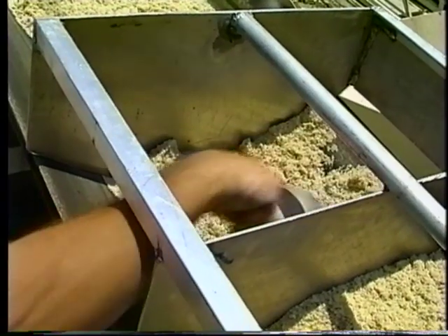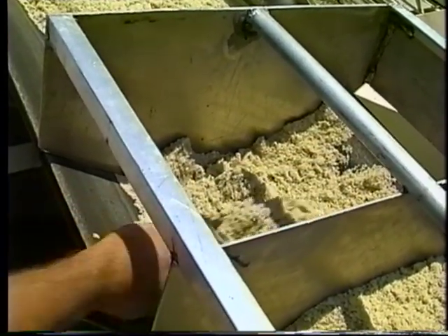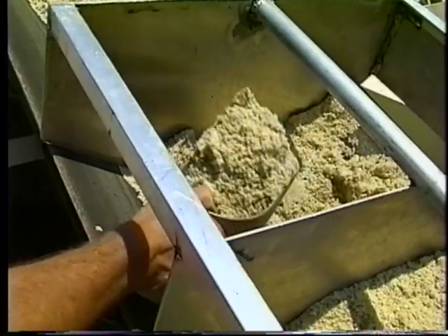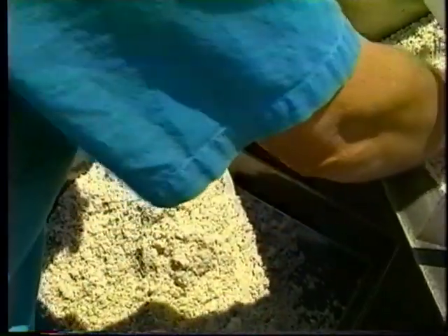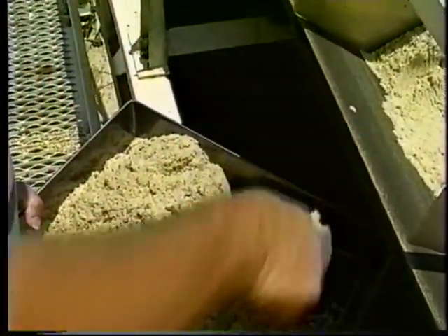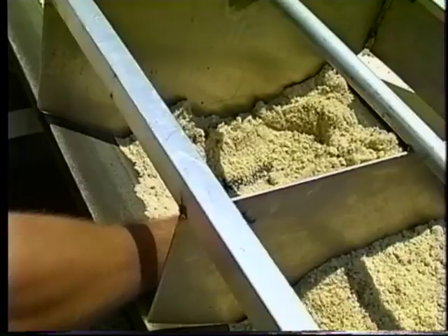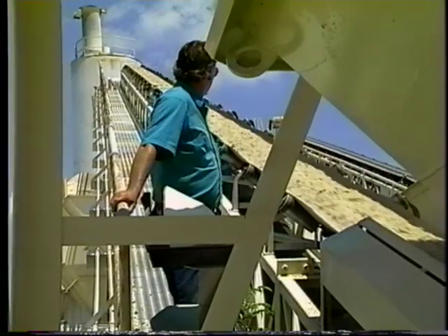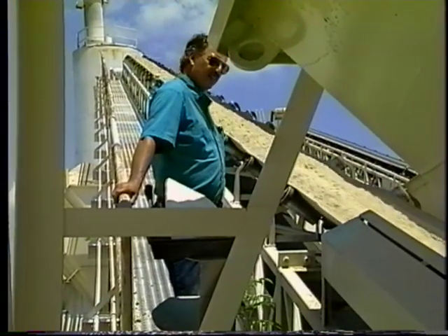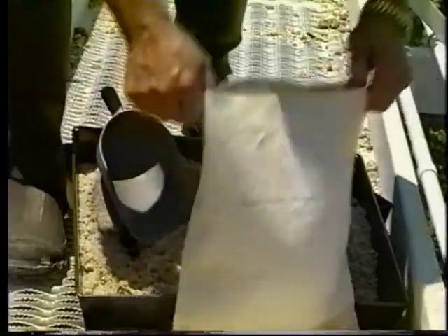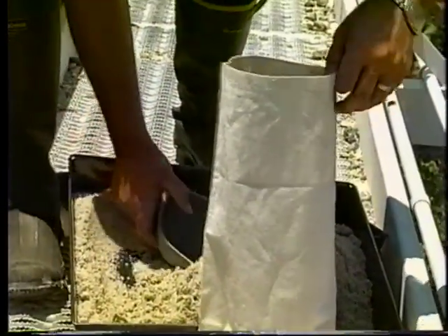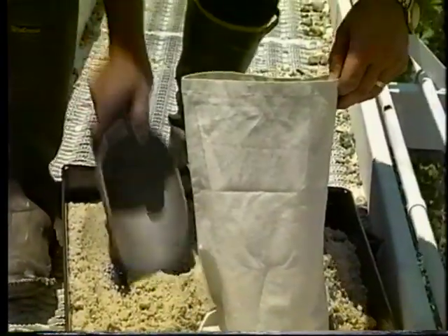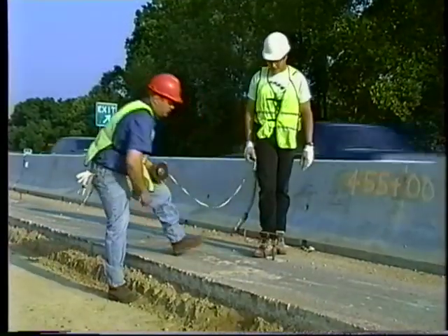Place the template through the material, making sure the template is in contact for the full cross-section of the belt. Remove all material within the template using a brush and pan to remove all fines. Remember that fines are an important part of the material and must be included in the sample. If the quantity of material obtained is less than the quantity required, obtain another sample. When you have finished taking the conveyor sample, place the material in a sample sack with the appropriate test report form. Now we'll sample from the roadway course.